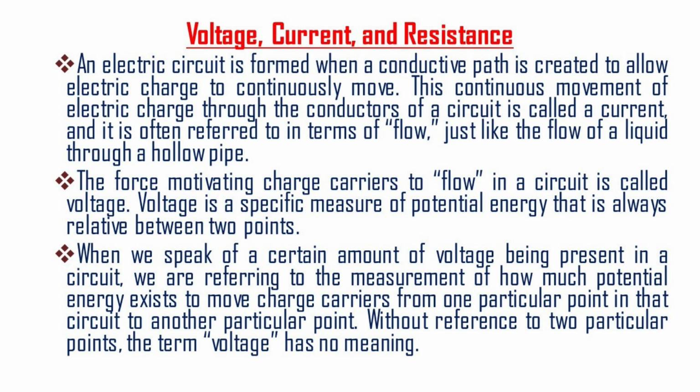Voltage is a specific measure of potential energy that is always relative between 2 points. When we speak of a certain amount of voltage being present in a circuit, we are referring to the measurement of how much potential energy exists to move charge carriers from one particular point in that circuit to another particular point. Without reference to 2 particular points, the term voltage has no meaning.